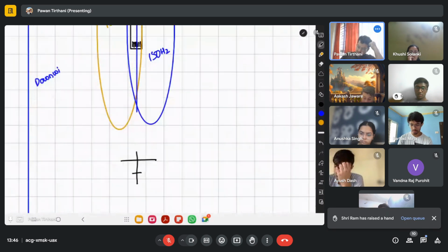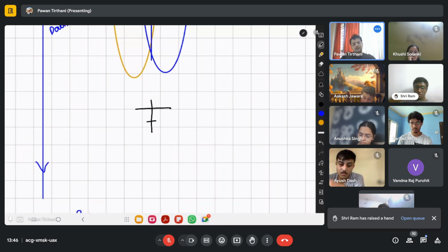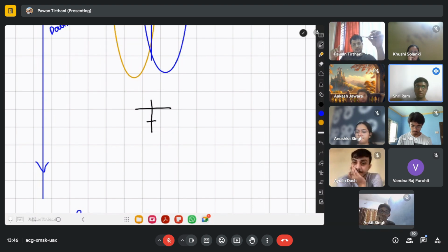Let's see. But the VHF antenna is vertical, right? That is the VHF comms antenna. Okay. Anything communication is a vertical antenna, anything navigation is a horizontal antenna. So VDF is exceptional, right? VDF and NDB are exceptions. Okay, and to some extent, the airborne radar is also exceptional. But at that point of time, we don't actually care about the polarity.